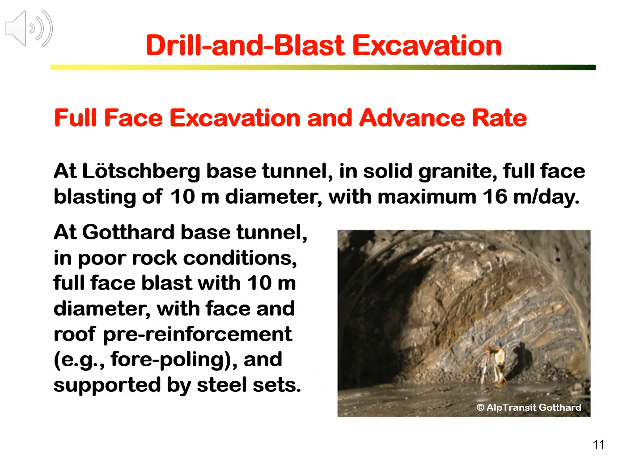For tunnels of small and medium size, full-face blasting is usually adopted. The Lötschberg base tunnel for railway use, with a 10-meter diameter, that is about 80 square meter cross-section area, used full-face blasting in solid granite with a maximum advance rate of 60 meters a day.